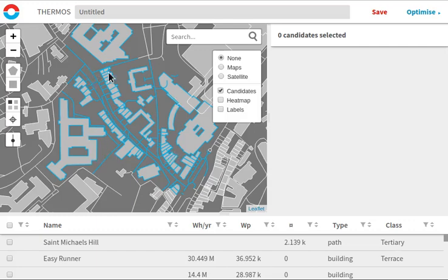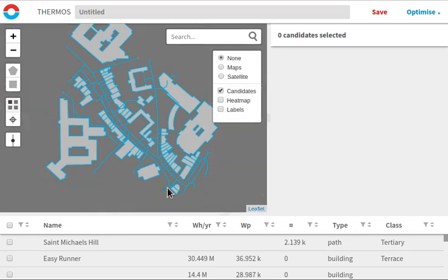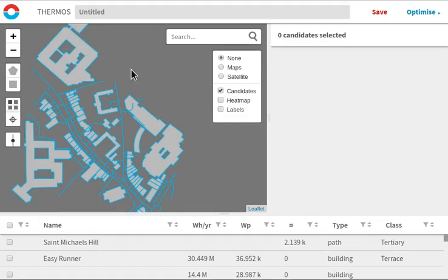Once you've made a selection of buildings like this and converted them into candidates, you might also want to turn off the display of candidates which are now extraneous to your consideration, which is what this button here does, where it says hide unconstrained candidates. Clicking on that shows us only the things which are in this table, so those are the things which we've colored in blue. So as promised, now that we've selected a bunch of candidates for consideration in a network, let's get THERMOS to evaluate a simple network which connects up these buildings in some way.